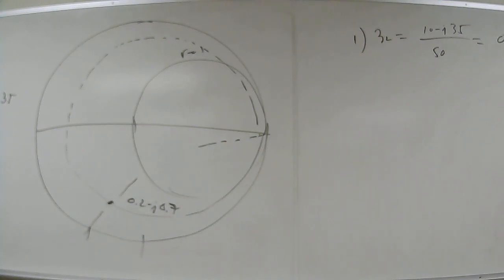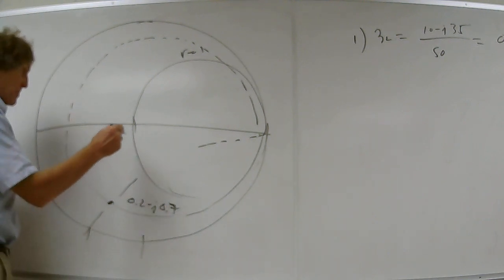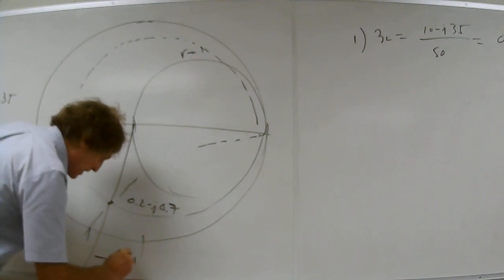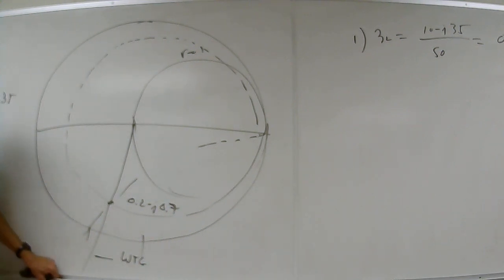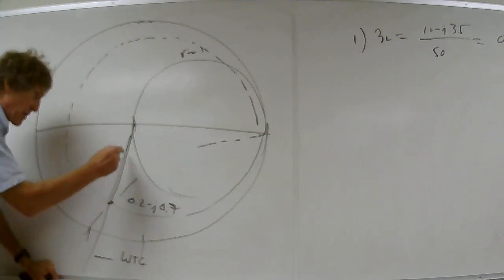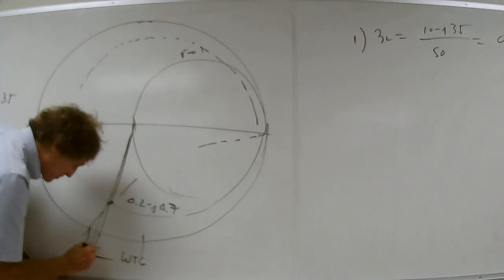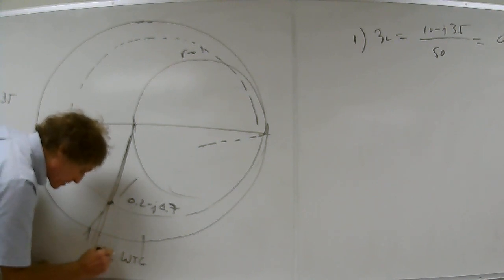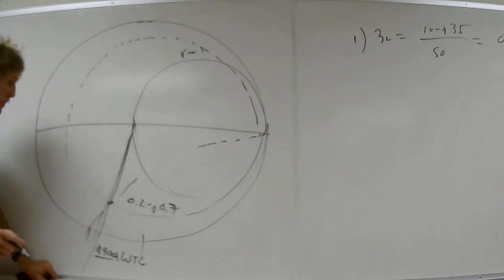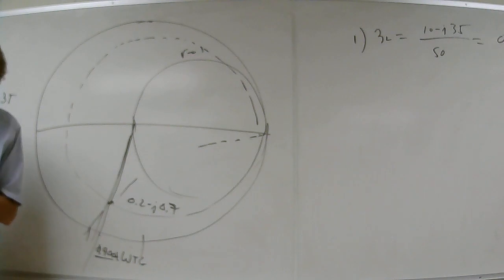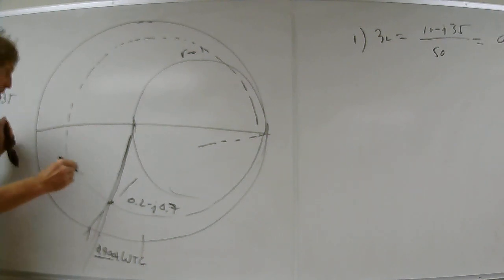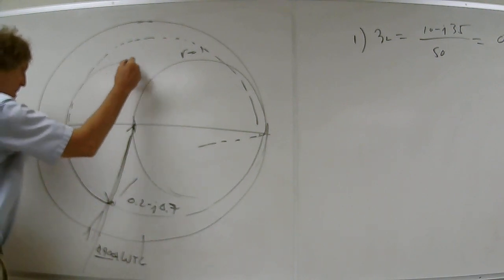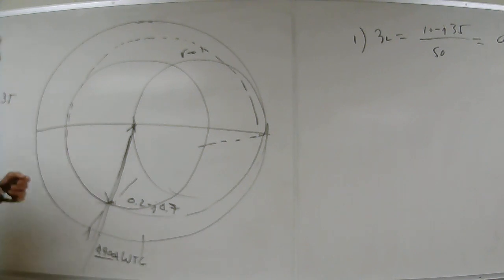Now the next thing you have to do, you can do this in any order you want, but I shoot a line right through there, out to the edge, and give me the wavelengths towards generator. 0.400. Remember, you go right through there and where this hits. 0.400? I think so. Yeah, I got about that. Okay, good. Now, next take your compass, some people are ahead of me, and just draw a circle of this radius here. You're going to draw something like this. Y'all with me?